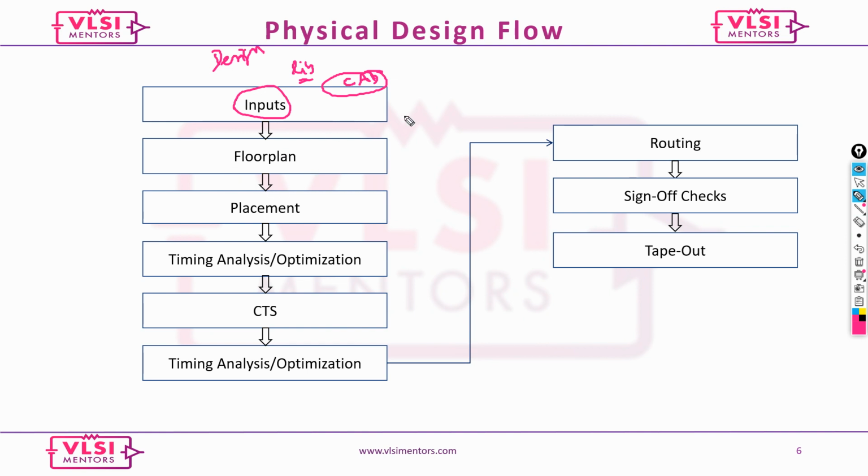So floor plan is basically, say, this is going to be your design. Now, where are you going to place your IO ports, and how are you going to place the logic? You may have IPs. Say certain IP you might want to place only in this area. So the whole thing is planning your design. The area planning, and then the next important thing that we look at is what is the utilization number that we have. All these things we do in the floor plan stage.